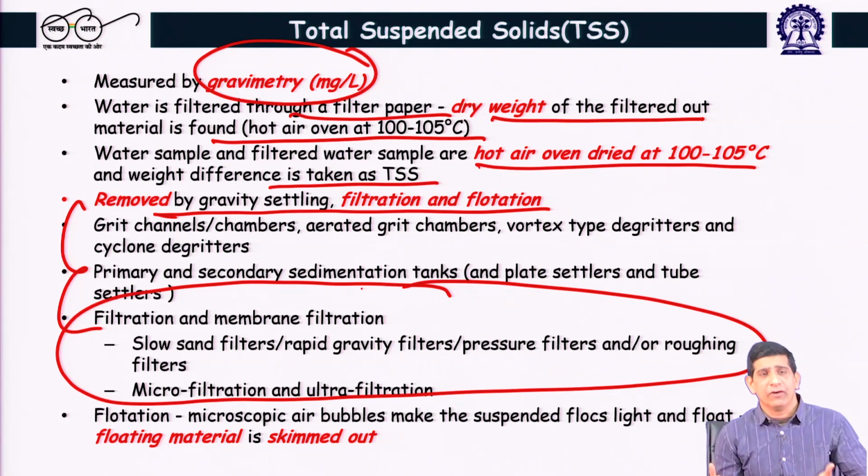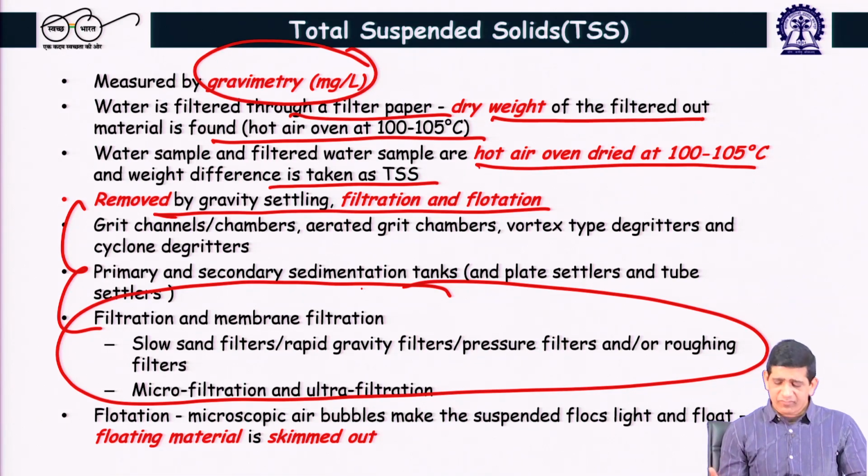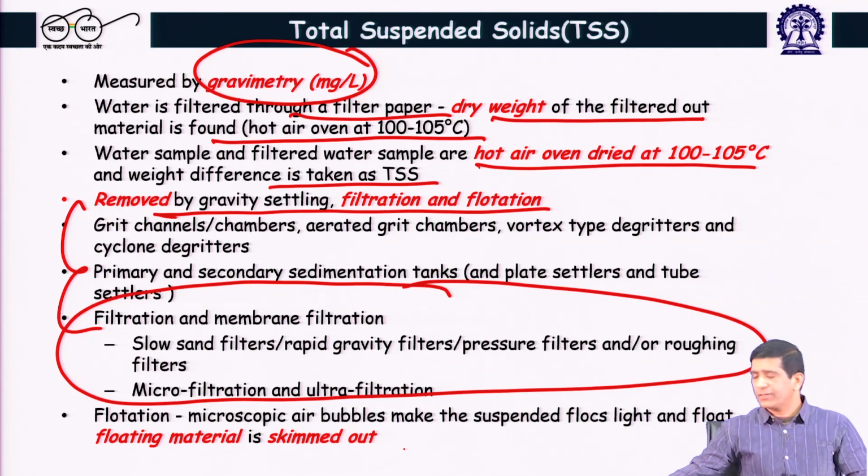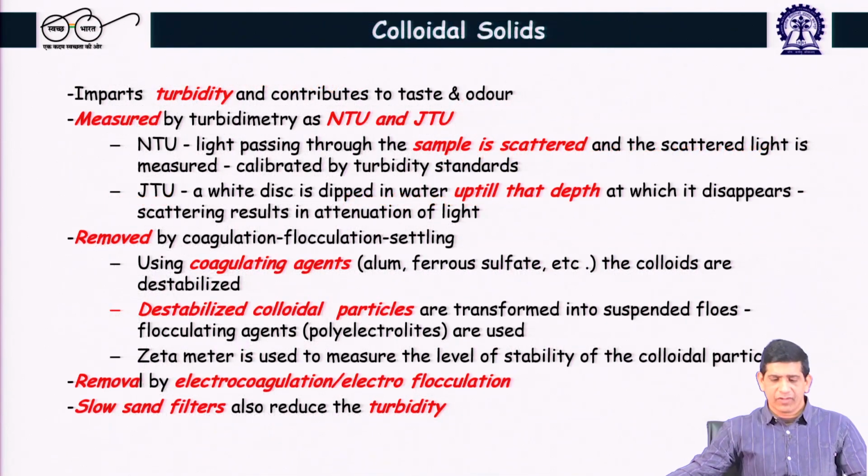If needed, we have to remove hardness, and so those are the things which are done in terms of getting the water treated. And before we put it into the water supply system, we have to treat that water further as well. Then colloidal solids: if you remove the turbidity, you can remove the turbidity using those colloidal solids. So, this NTU is a turbidity unit.